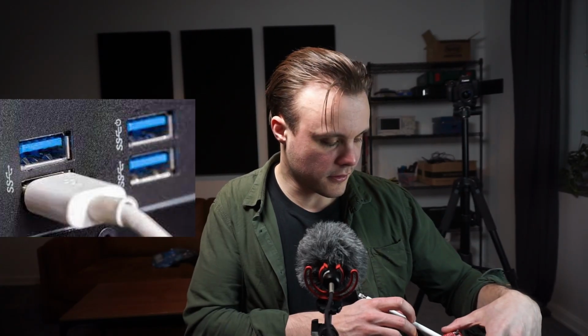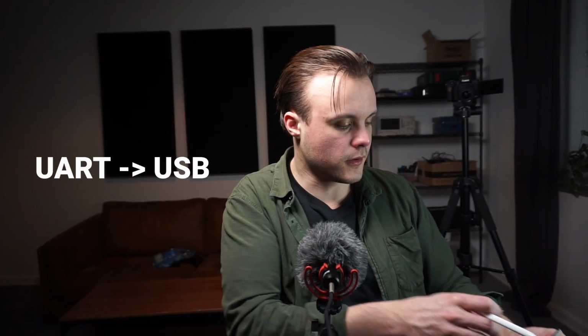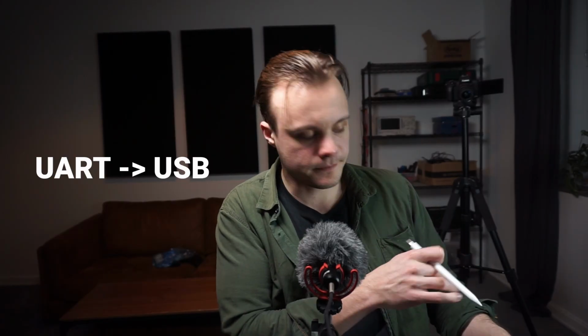And for this reason, to connect this microcontroller to my computer, I need to have a separate converter chip, a so-called USB-to-UART bridge that translates the traffic from the UART to USB. And this chip is going to have a corresponding driver on, in this case, Linux, that's going to show up as a serial device that I can talk to.